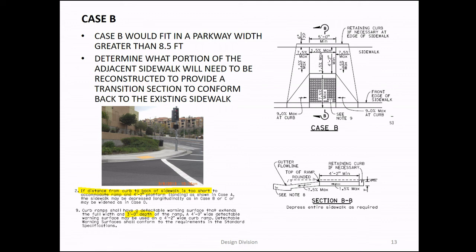We're thinking 2 feet should be more than enough, because we're not improving the access here. We're just trying to reconstruct the curb ramp to standard. So about 2 feet should be fine, because this should take care of it. They should set from here to here 7.5%, whatever that is, and then just enough for them to transition.